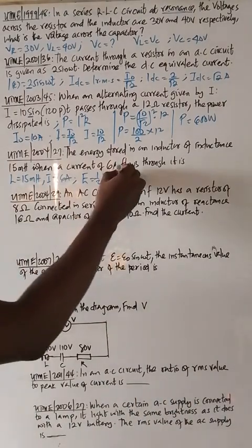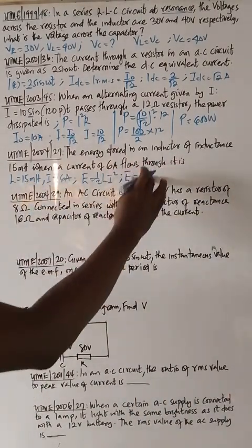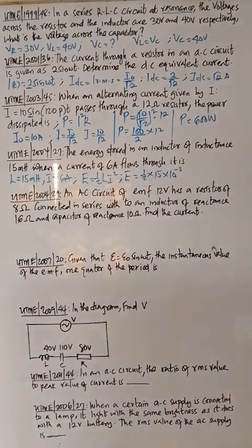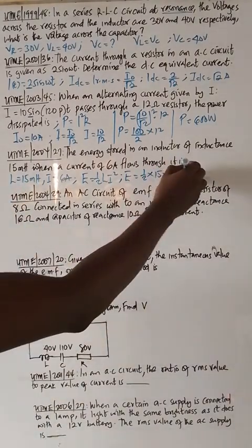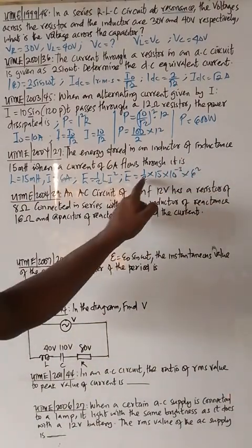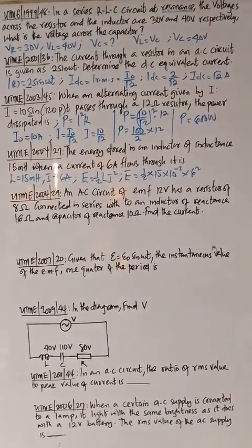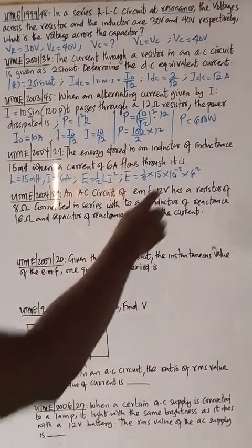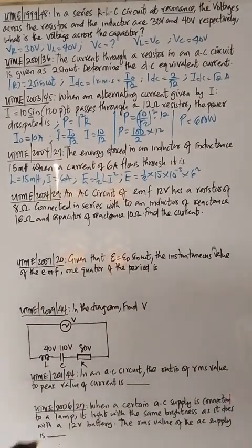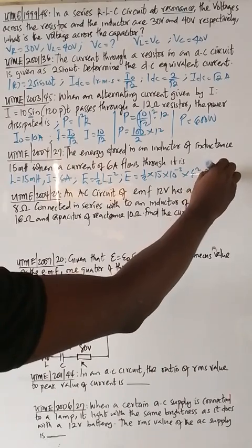Resistors. So from here, you can get our E, which is half. The L is what? 15 millihenry. So that's 15. What's milli? 10 to what? Negative 3. Then times I squared, 6 squared. So 6 squared is 36. Half of 36 is 18. So 18 times 15 will give you what? Yes, 270. Times 10 to the minus 3, which is 1 over 1000. So 270 over 1000 will give us what? 0.27 joules.